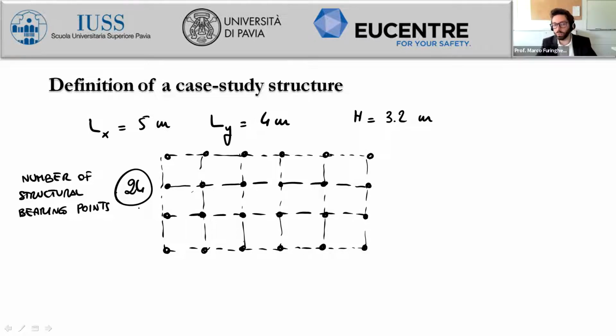And also, according to this definition, there will be a more direct application of the vertical load to the devices, simply because the columns are vertically aligned with respect to the isolators. So, there are a number of applications where this doesn't happen. First, one of the most famous within the Italian territory is Progetto Case at L'Aquila.